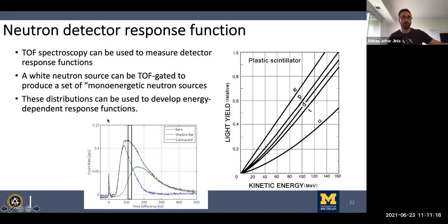Now, there is a question on the electron detector. How are the remaining positively charged ions affecting my signal? In this case, it really goes into how your detectors are made. There are certain types of detectors, gaseous detectors, and in these gaseous detectors, your heavy charged particles and your electrons are ionizing your gas. That ionization is actually what constitutes your electric signal. So it really depends on the detector type, and what type of electronics we are using to collect the signal.